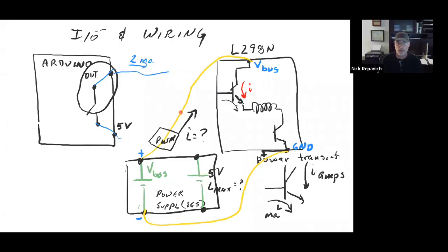Or you can start looking at your motor. That's a good indication of what size wire you should attach to your motor wire. At least as big as the motor manufacturer put on there, right? So part of your wiring is, when I look at it, I'm going to look to see if you paid any attention to the wire size that you hooked up. But that's one of the reasons you got to calculate current. Not only blow it up, but also to choose the wires. Okay.